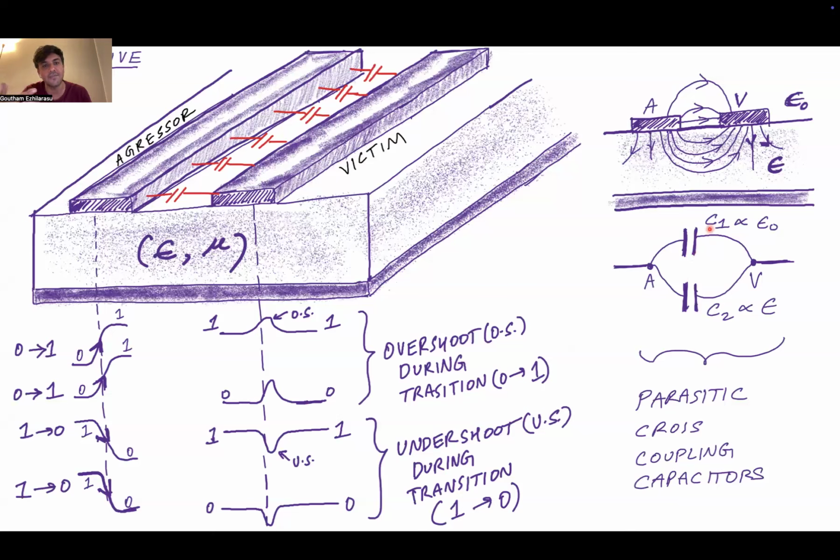And what happens is, as the frequency increases, more and more electric field gets confined in the material, which has a higher dielectric constant because it has a lower value of capacitance. And hence, the net capacitance, the parallel combination of both the capacitors, is now actually going to go up with frequency.